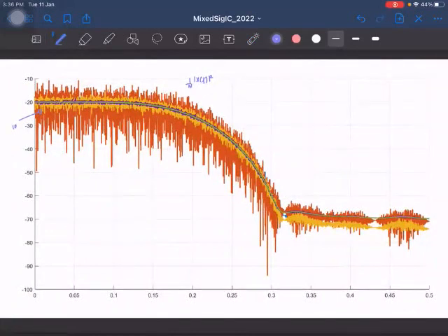So one exercise for you is to think about how I would have generated this sequence. In MATLAB, I can easily generate a sequence which has a constant or white power spectral density. From this sequence, say if I call it x of n, think about how I would have generated this kind of frequency-shaped power spectral density, or a sequence which has this kind of power spectral density.